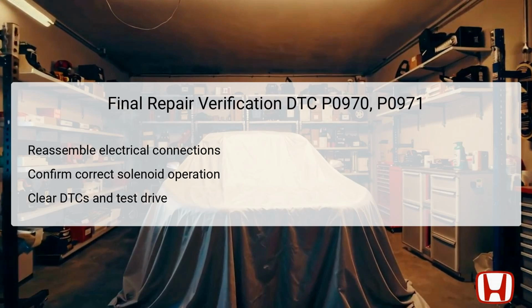Following these validations, use the Honda Diagnostic System (HDS) to clear any DTCs. Finally, perform a test drive to confirm that the symptoms have been alleviated and that no diagnostic trouble codes reappear during operation. This comprehensive final check will help ensure reliability and performance of the transmission system.